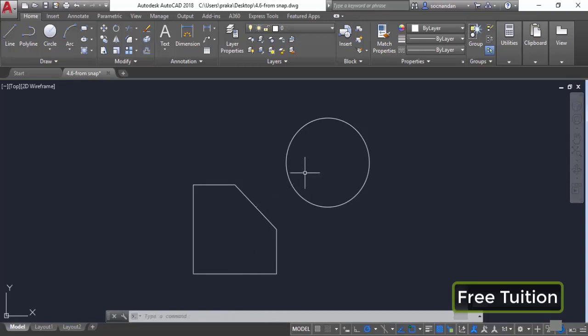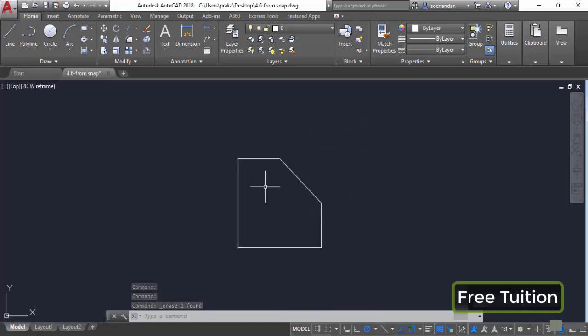So let's repeat this process, but this time instead of making the circle here, I'll make the circle somewhere inside this geometry. So once again, let's assume that we want to make a circle on this side, and in this case we want the distance to be equal to 3 units from this point, or let's make it 5 units from the midpoint, and it should be in this direction, and the angle which it should make with respect to the x-axis should be 235 degrees.